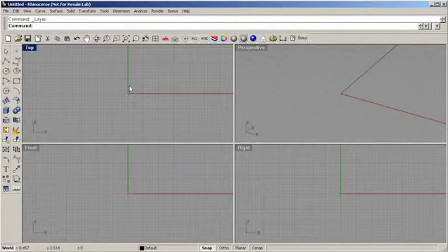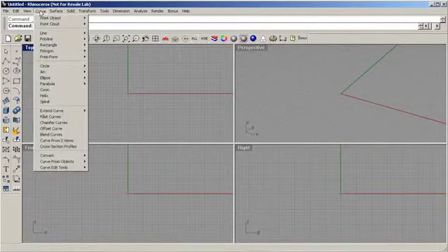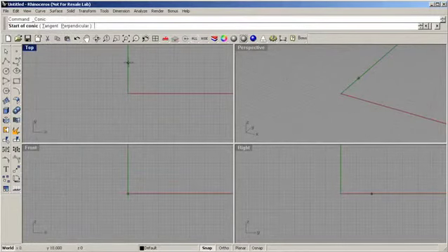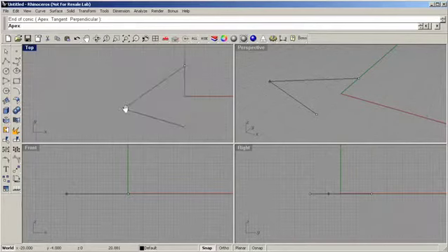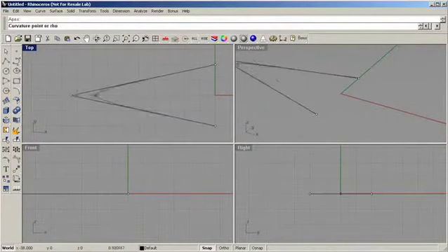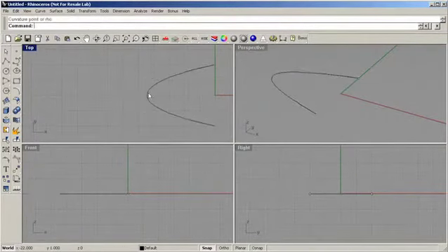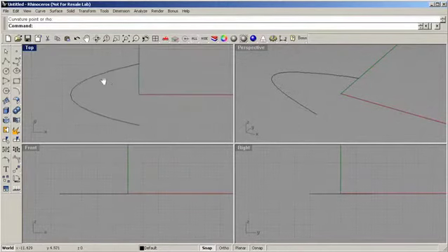This is the Rhino environment, and we're going to start by making a model of the reflector. To do that I'm going to be working with a menu system up here, curve, conic, and during this demo I'm not going to explain every last detail. So this is going to be primarily visual. What I've done just now is to create a curved line.